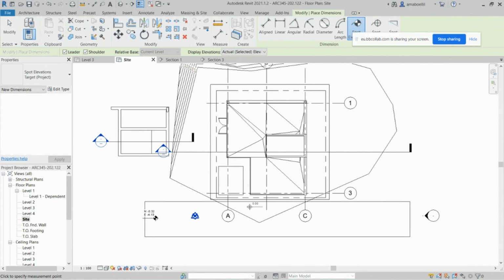And of course, because this has to do with the drainage and water runoff and other things, you have to adjust this level and give it the mark here to tell you what the level is. And whenever we have stairs or ramps outside, you have to place this before the ramp and after the ramp, and this before the stair and after the stair to tell you how much elevation we would have.